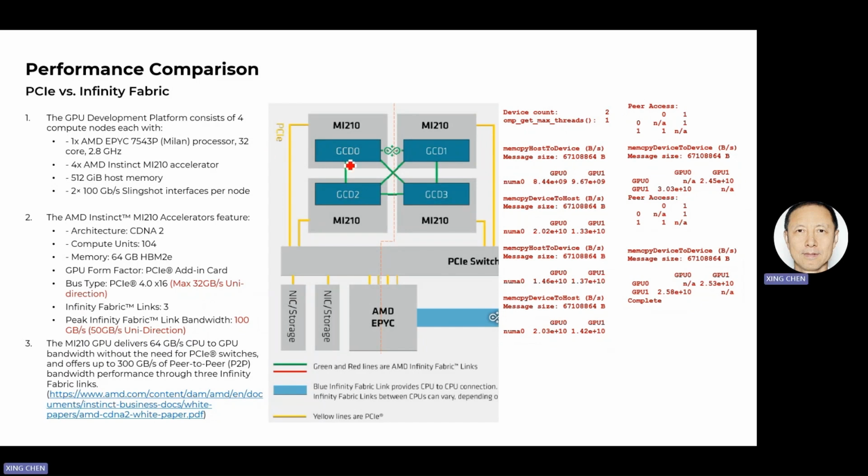Let me start from where it has been cut. What I'm saying here is that the left-hand side column has been tested. The data are already in the memory. Now we can measure the memory bandwidth. Now we can measure the bandwidth between two GPUs by going through the Infinity Fabric. So in each NUMA node, we have two GPUs, the GPU 0 and GPU 1.